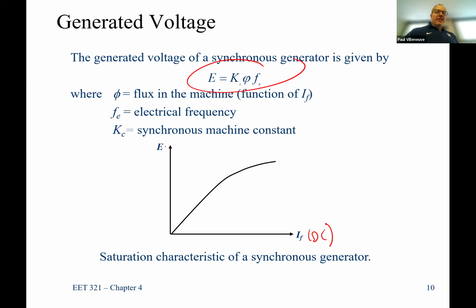that's going to create a back EMF voltage. This is an AC voltage over here. That's the voltage that is across those windings. So I can look and see if I drive so much field current, here's what the voltage, now this is internal to the machine. This is across the windings. It actually isn't the terminal of the machine.